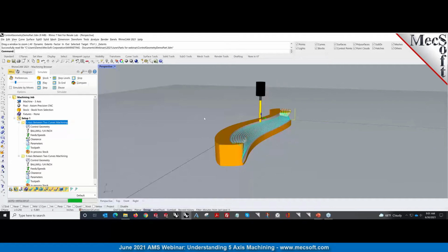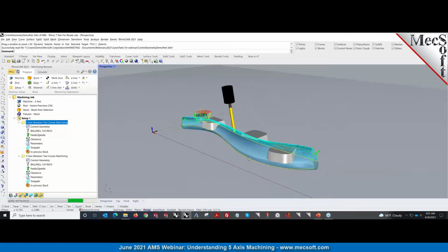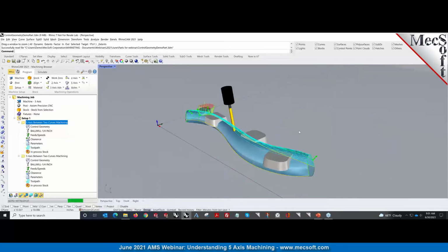In index machining, what we are doing is different. We are locking a particular axis. We are rotating the tool axis. Let's say we're doing an index machining. We're coming in from this direction. And we're locking that tool axis in that orientation, not position, just that orientation. And then machining in 3-axis mode. So that is what index machining is, as opposed to continuously varying the toolpath method in 5-axis. Hope that makes sense.